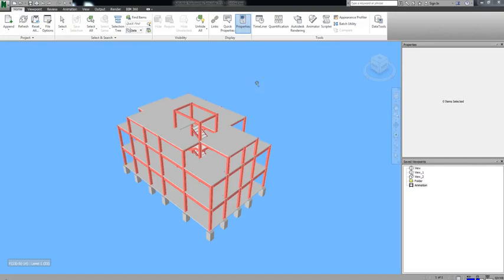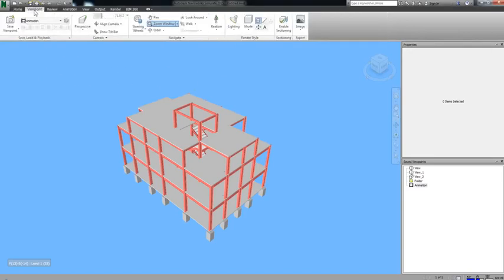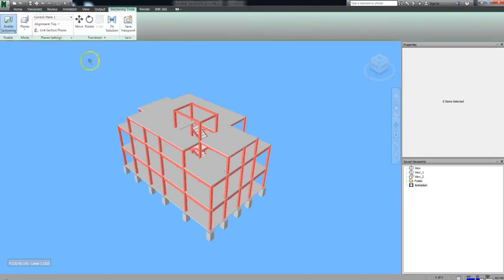In order to activate sectioning, go to the Viewpoint tab. Under the Sectioning panel, you'll see a single icon called Enable Sectioning. If you click on that, you will be able to incorporate sections into your viewpoints. When you enable sectioning, a new series of options will appear in the ribbon. One of these is Mode, which allows you to create sections either based on entire planes or out of boxes.